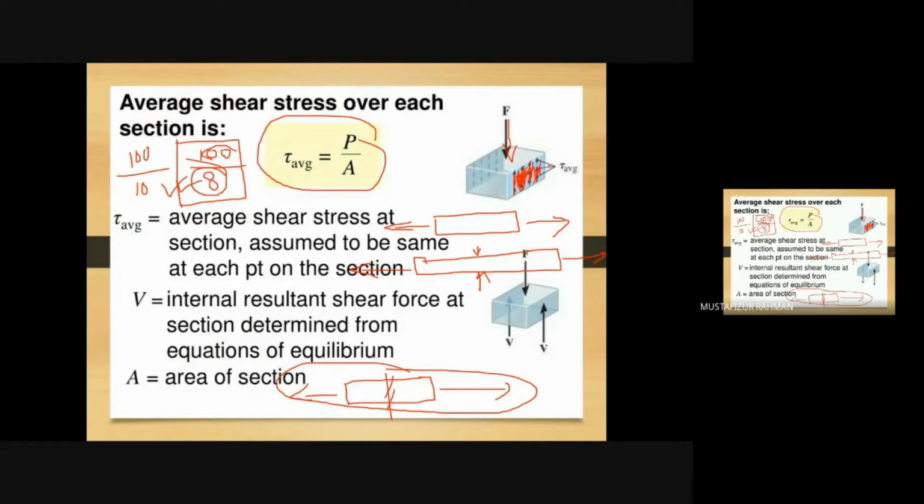When we first discussed, we didn't mention this. So the stress strain curve was something like this. But if we consider the actual stress, because the area is also decreasing, what we were doing was considering the same initial cross-sectional area, and the material is kind of failing.